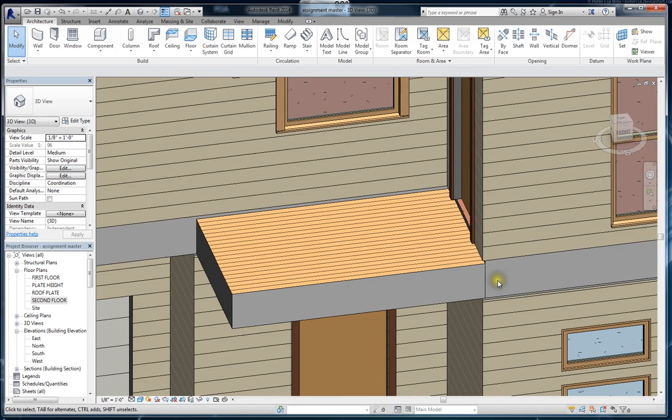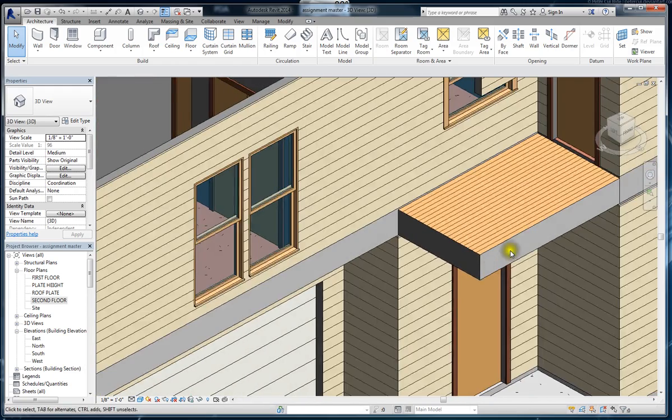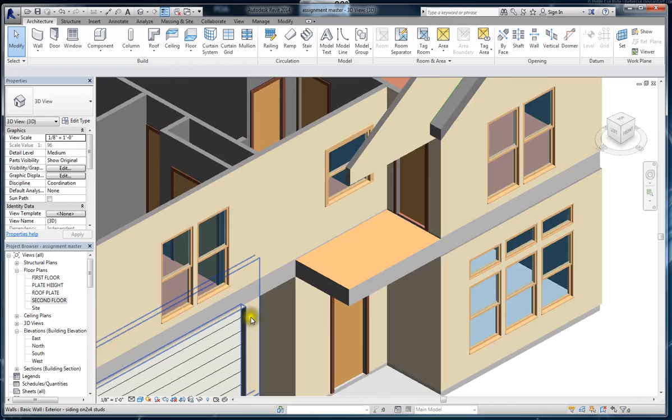But trusses, they come in whatever depth that you want. So we use 16-inch trusses for the floor. So on this one, I'm just calling 14 inches, 2 inches lower than that one. This could be 12-inch, it could be 13-inch, but usually it's an even number: 8, 10, 12, 14, 16, and so on. So that's why we did a 14-inch, so we can have a 2-inch step down and have that waterproofing happening at the door.